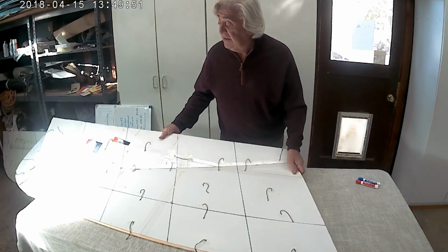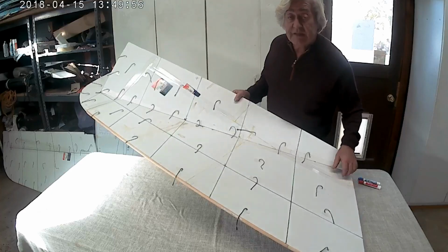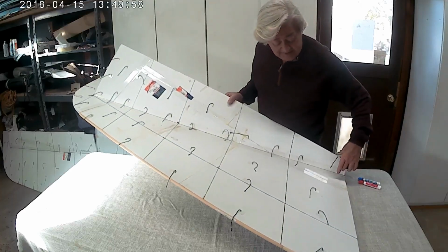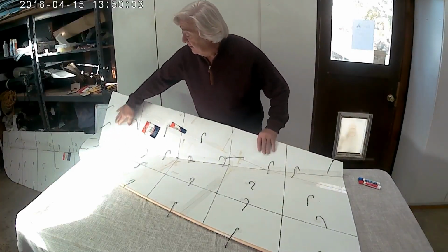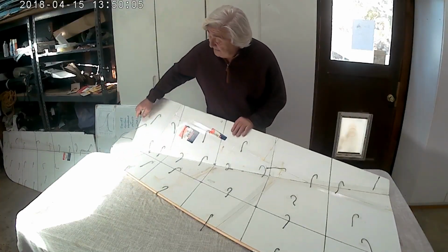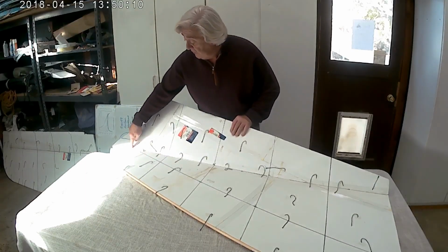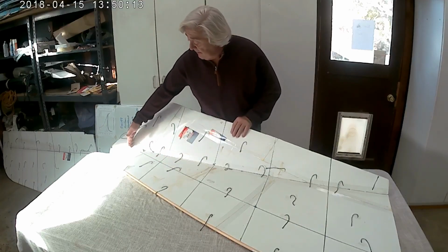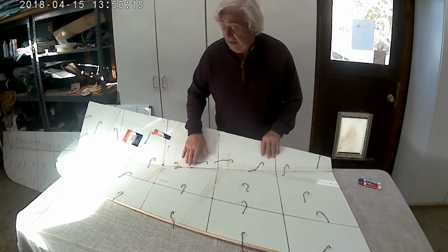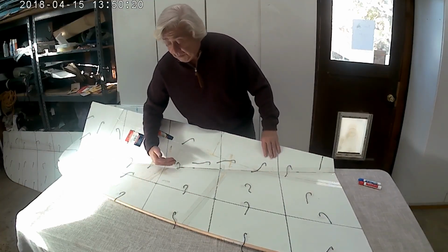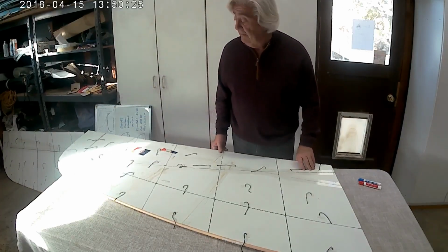But here is the third shape that I tested. I hope this is in view here. You'll see it has a huge reverse taper. The elevon has a very narrow chord here at the root and a really wide chord out here at the tip. In fact, the elevon at the tip comes all the way up to where the spar would be on my wing. This is where the spar is, right here, and the elevon at the tip is at the spar. So, huge reverse taper. In fact, this hinge line is not quite, but almost perpendicular to the incoming flow. Close to it. Not quite.